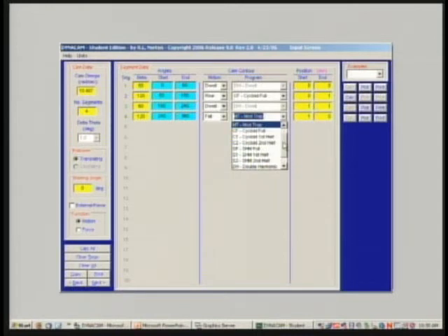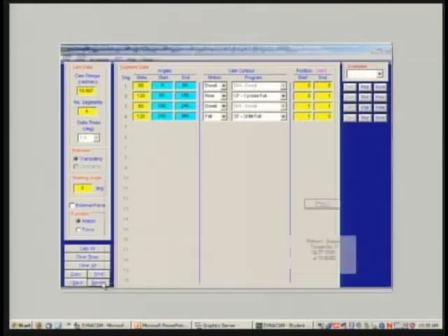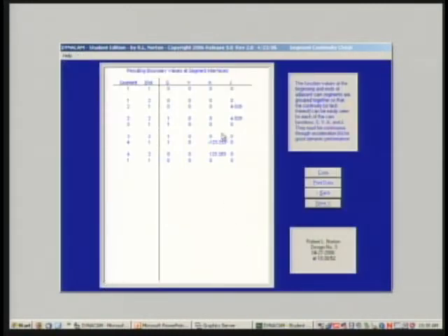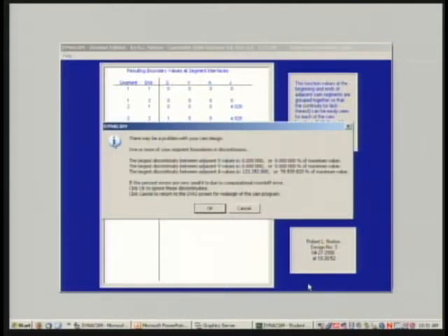Well, let me show you a bad example just to reinforce this whole issue of the fundamental law. I'm going to pick a simple harmonic on this one. I'm going to recalculate, leave this. Now look what we see here. The acceleration between the dwell, which is segment 3, that's the high dwell, and the fall is discontinuous because I've chosen an inappropriate function. The simple harmonic motion doesn't obey the fundamental law.